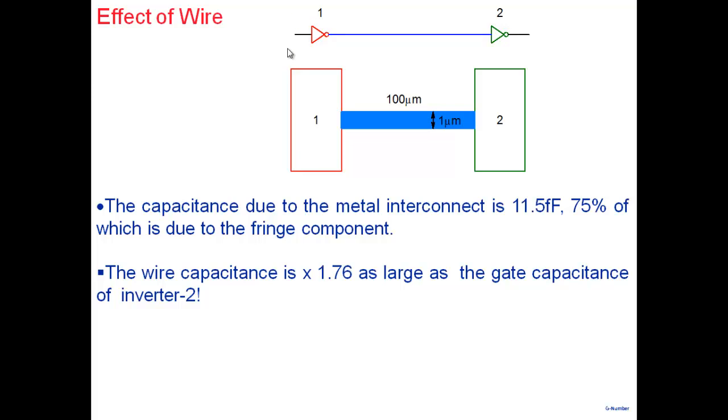You may think that your IC will run at 500 megahertz. It may run at 250 megahertz because the capacitance is twice as large. You have to examine the critical paths, and in the critical path, there would be a wire also there.